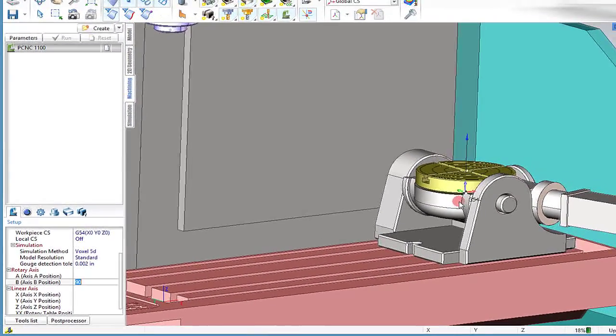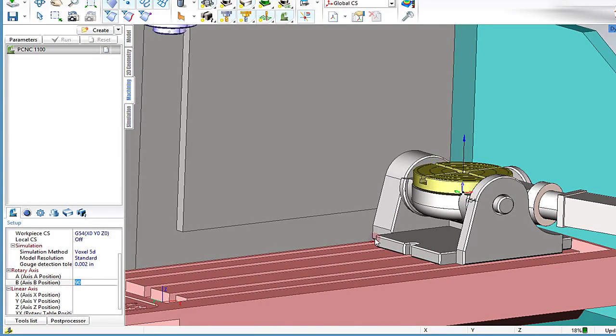And since this model that you see here is not a super accurate model, you will need to set up your job and your material and then use the calipers to find out where the top of your material is located. And then what you will need to do is go into the real world and make that measurement, figure out the difference, and then you may have to move your material to match that difference off the center of rotation.